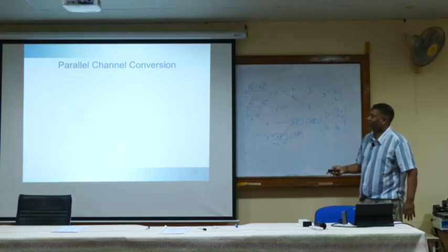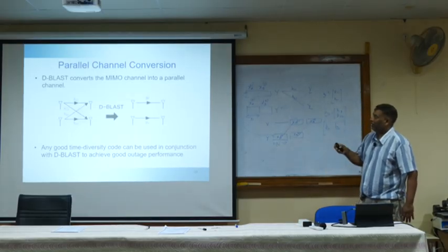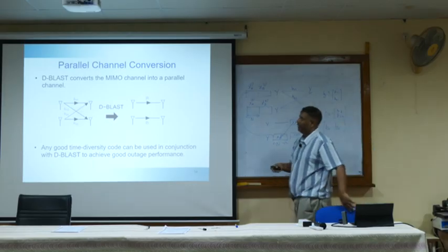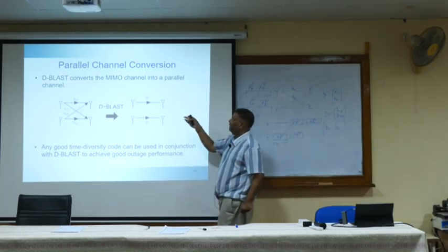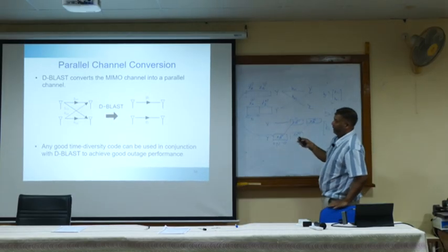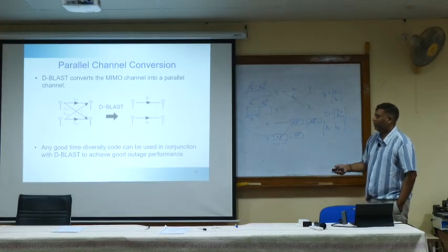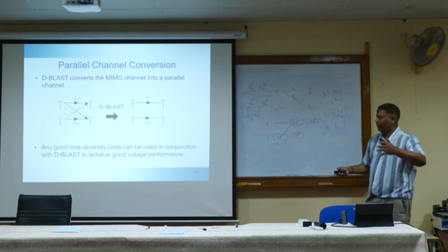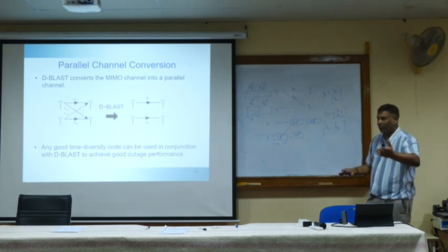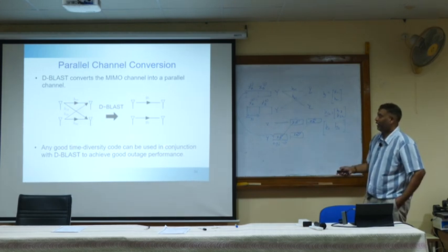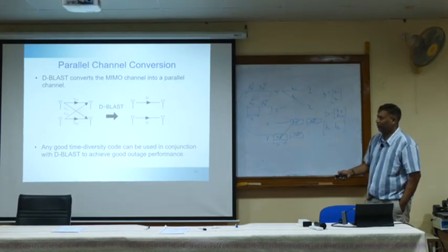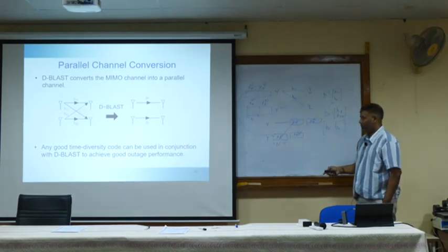So what D-BLAST is doing is converting the MIMO channel into a parallel channel and a good time diversity code. Time diversity code means your LDPC code or turbo code can be used in conjunction with D-BLAST to achieve good outage performance.